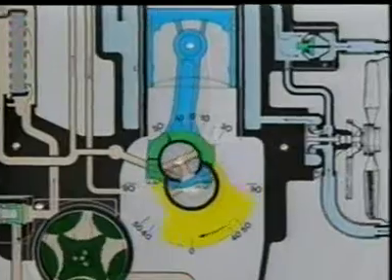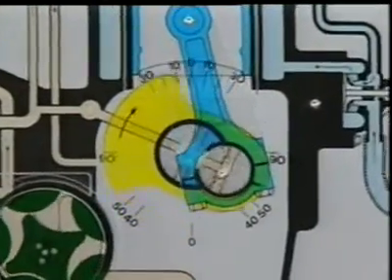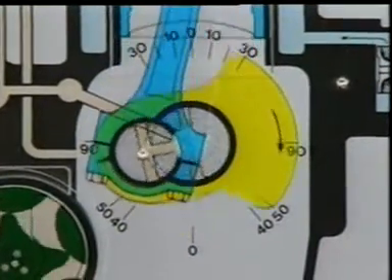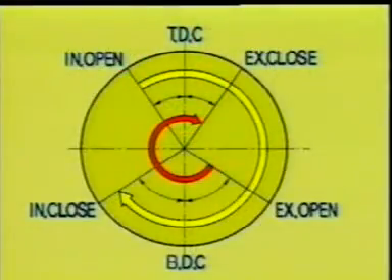The 4-stroke valve timing diagram shows at which angle of rotation of the crankshaft the valves are opened and closed. It is similar to the port timing diagram used in the 2-stroke engine and demonstrates when intake, compression, combustion and exhaust occur.